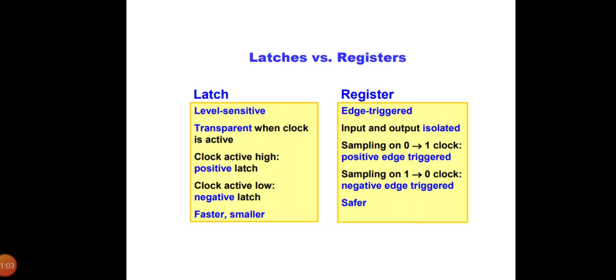When the clock is low, the input sampled on the falling edge of the clock is held stable at the output for the entire phase, and the latch is in hold mode. The inputs must be stable for a short period around the falling edge of the clock to meet setup and hold requirements. A latch operating under these conditions is a positive latch.